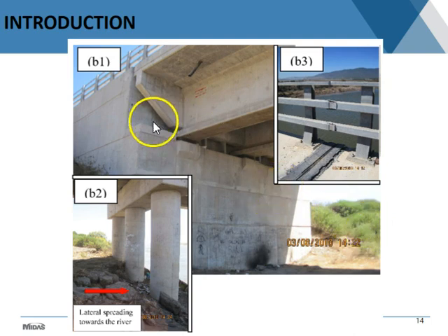As you can see here in figures B1, B2, B3, really the amount of residual lateral displacement was rather minimal. Here you see the handrails of the bridge that overlapped. I mean, they knock each other, creating these small failures here, okay, with displacement that from our estimates was not larger than 2 inches or so.